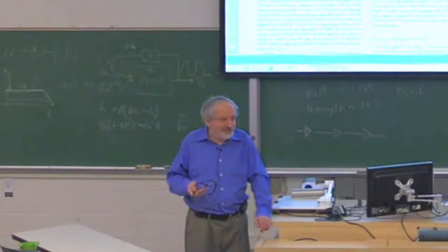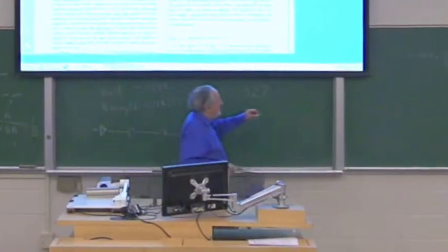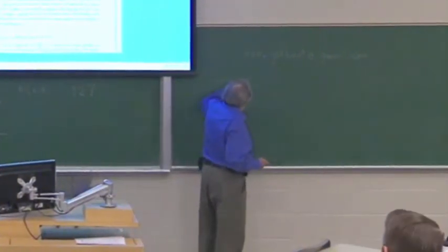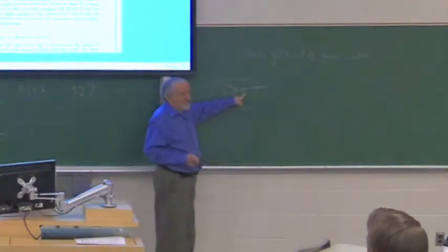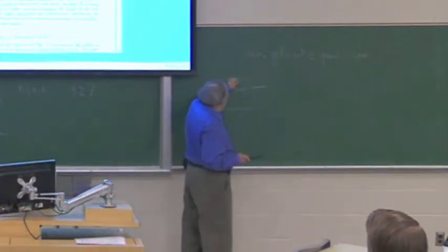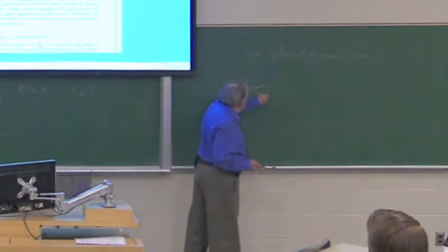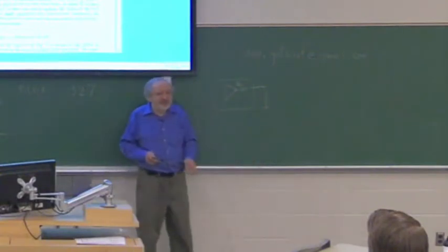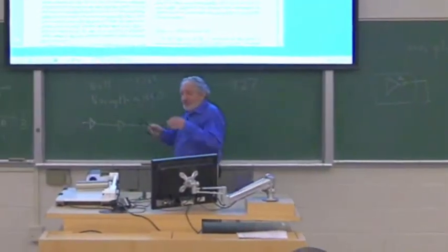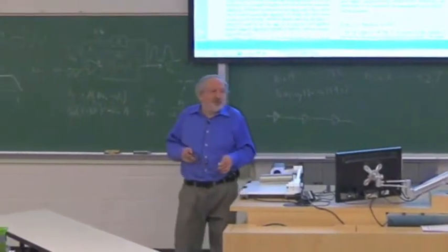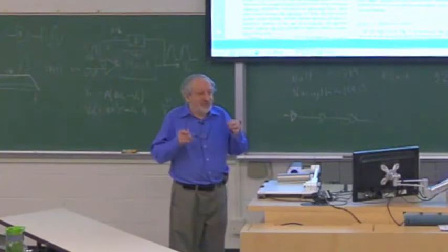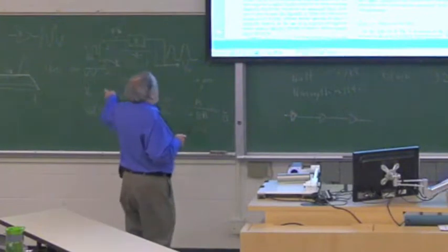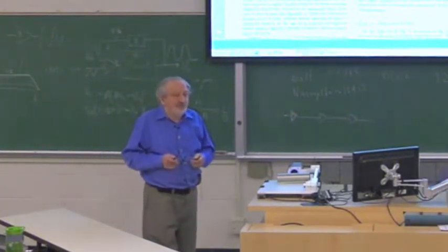Makes sense, right? Because if you have a black box, which is an amplifier, with a high output impedance, it looks like an amplifier with a resistor in series. That resistor is Z out, the output impedance. As soon as you load it, you get a voltage divider, and the voltage drops. So in an amplifier or a power supply, you want as low an output impedance as possible, so the voltage is stable. So how does negative feedback affect the output impedance?